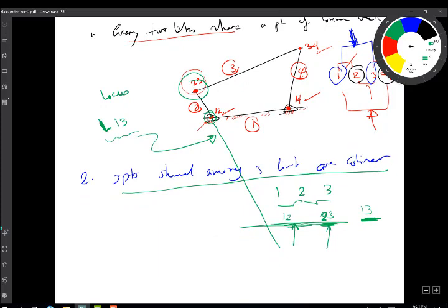If I want to find point 1,3, I have to find another line, another locus, and then find the intersection of the two loci. So if I come from the other end of the linkage, I have two points here: point 1,4 and point 3,4. The common number here is 4, so the missing point is 1,3 again.